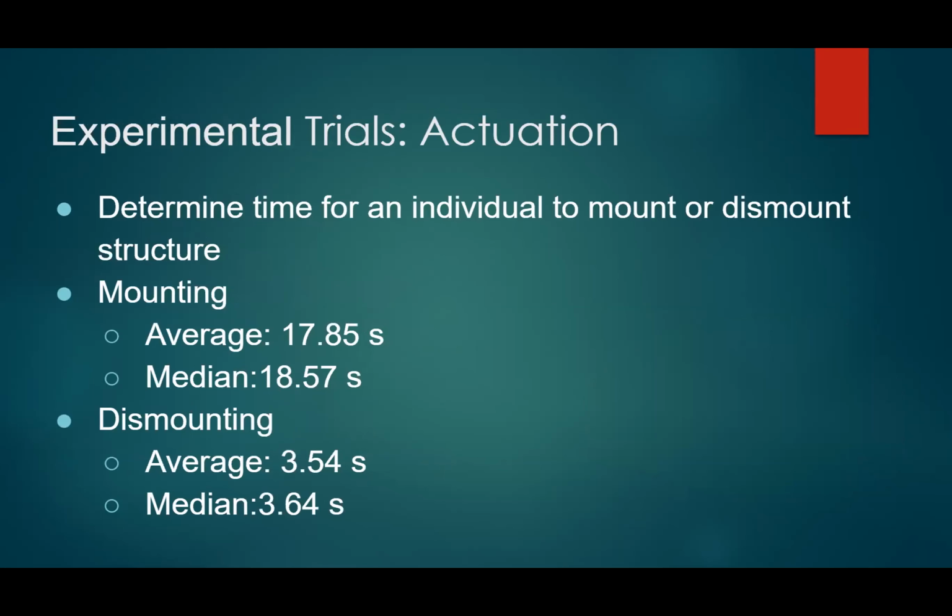So here are some of the trials that we have, and after this slide, we're going to follow with a graph so you can see it more clearly. While we were mounting and dismounting the enclosure onto the hitch, you can see that the mounting process takes a little bit longer than the dismount, and this is due to the fact it's harder to see the roller pins get into the slides. So we actually accommodated this with the ergonomic handles that we added. So you saw a picture of the ones we had on it and then the ones that we added on it, making a total of 4 handles now, which actually helped quite a bit.